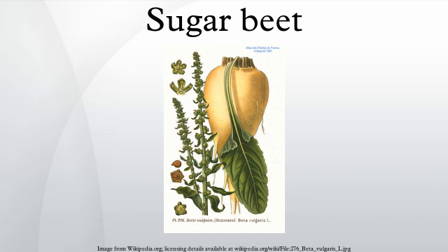Each load is weighed and sampled before it gets tipped onto the reception area, typically a flat pad of concrete, where it is moved into large heaps. The beet sample is checked for soil tare, the amount of non-beet delivered, crown tare, the amount of low-sugar beet delivered, sugar content, the amount of sucrose in the crop, and nitrogen content, for recommending future fertilizer use to the farmer. From these elements, the actual sugar content of the load is calculated and the grower's payment determined.